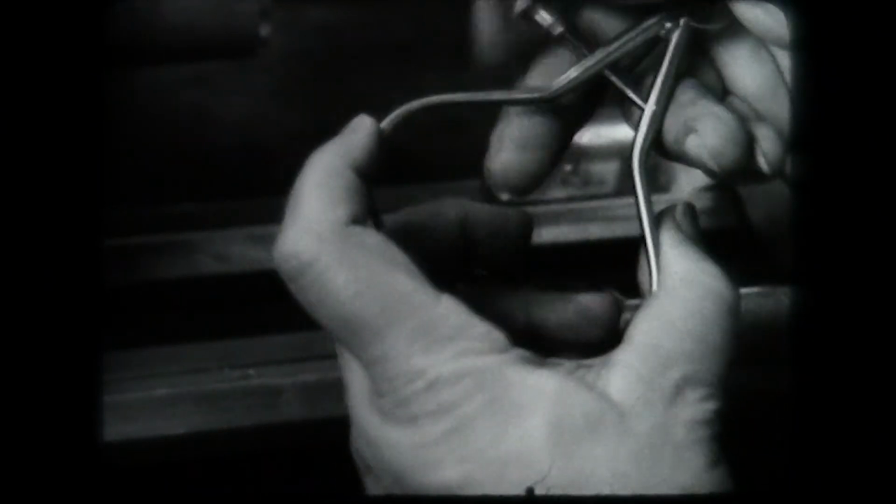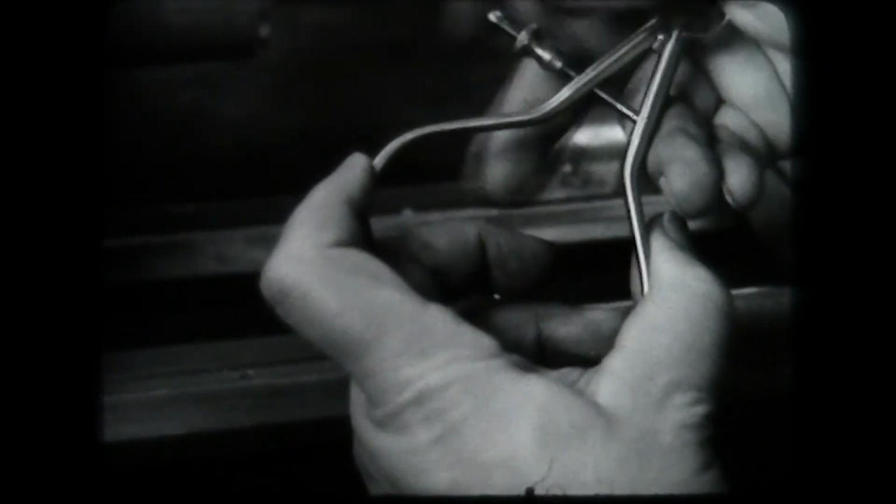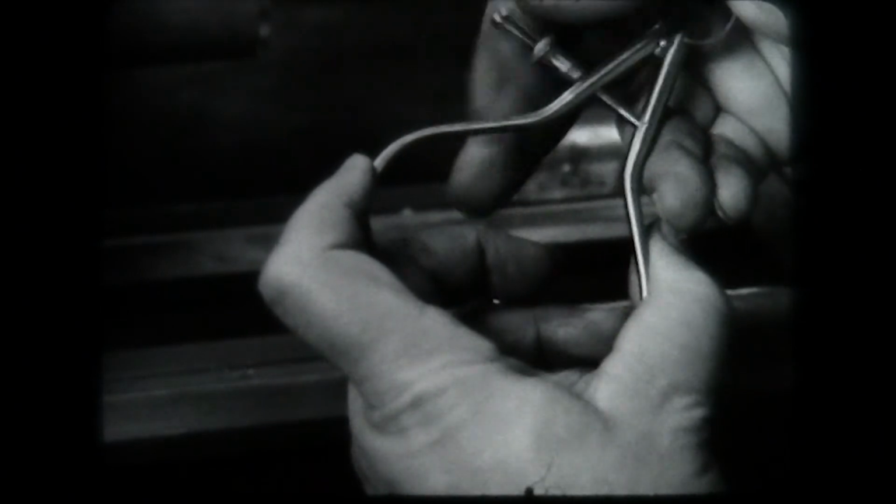If the outside caliper has to be brought from a wide setting to a small one, less wear of the adjusting screw and nut will result if the 2 legs are pinched together. The nut will turn freely and an easier and quicker adjustment will result.